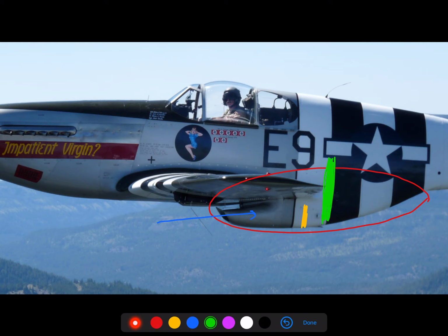And then we have our engine coolant radiator, which sits right behind it in what we call the doghouse back here. Now, interesting to note, this has two styles of cooler. We have a coolant radiator that's parked back here, as well as our oil cooler up front. So we have cooling being achieved from two different directions. The one thing you'll notice here is this little door that's on the bottom of our scoop. That is specifically for regulating the amount of airflow that can pass through that oil cooler.